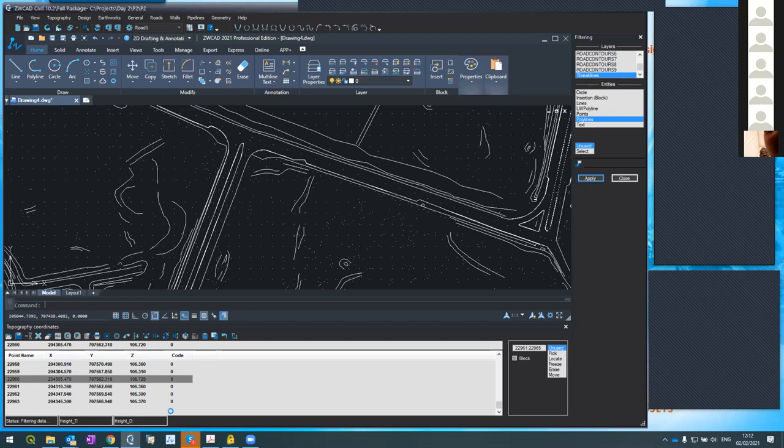It's a very heavy process, but since we are doing it only once as a preparation of the surface, there's no cause for alarm. So again, what I'm doing now is taking all these 3D polylines and converting them into break lines. We learned the importance of break lines in the first lesson. You can practice it later on. I will send you all of this file. Okay, now the process started. You see, only now you can see the progress bar. You can see it below.